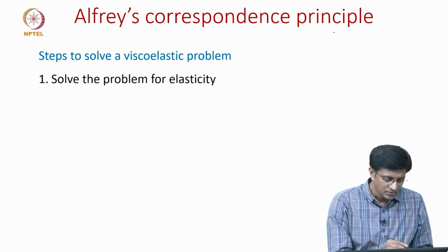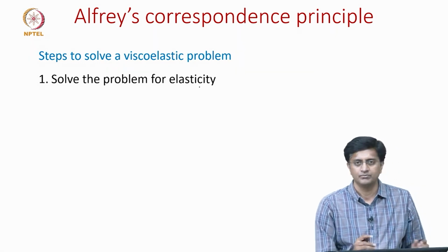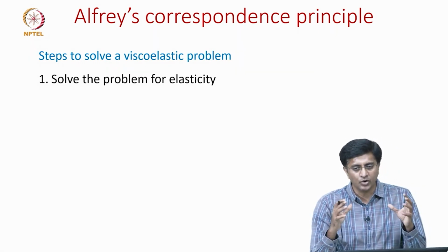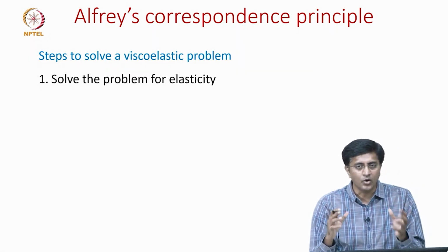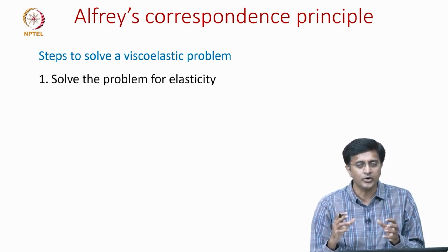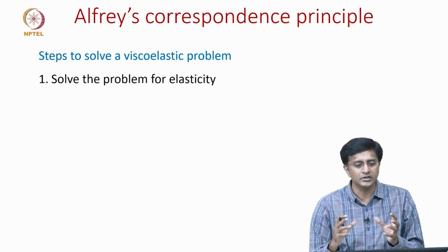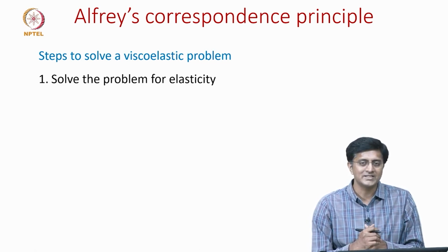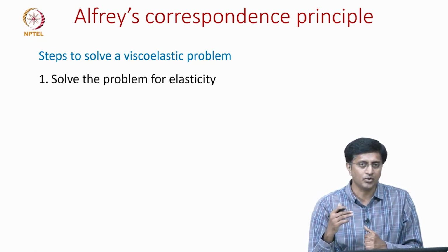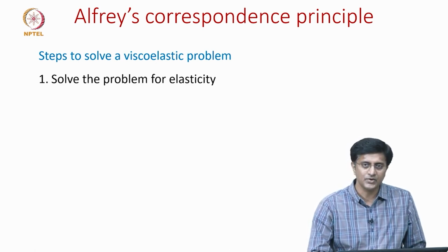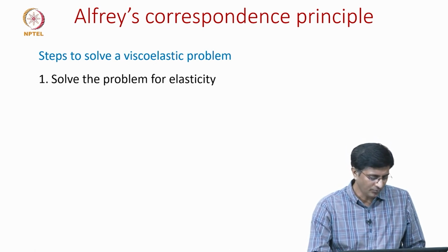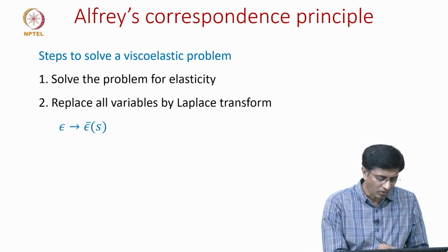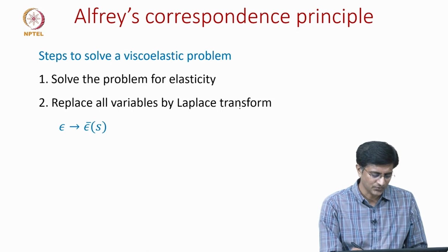So, first solve the problem for elasticity. So, meaning you know what are the loads applied on the body, what are the boundary conditions, then solve it in the elastic domain, or applying elasticity find the solution to that problem. Once we find the solution, then what we do is we replace all variables by Laplace transform.